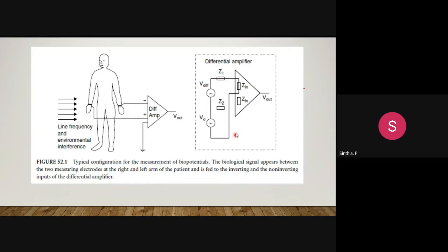For the common mode signal to be completely rejected, Z1 should be equal to Z2. The related voltage drops show a difference if the source impedances are unequal. So this generates a differential signal at the amplifier input, which of course will not be rejected by the differential amplifier.